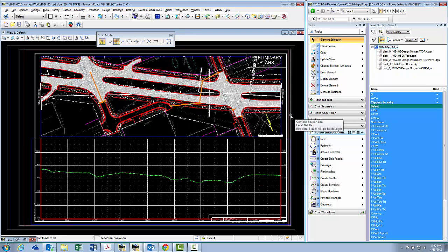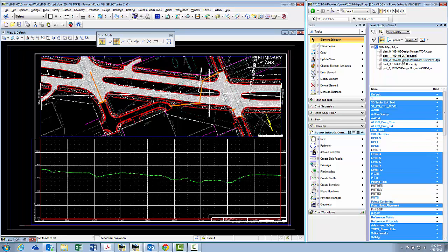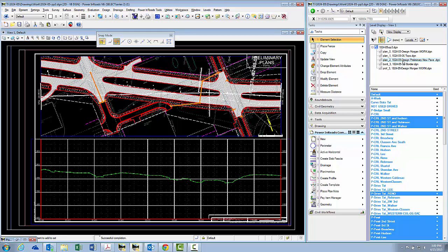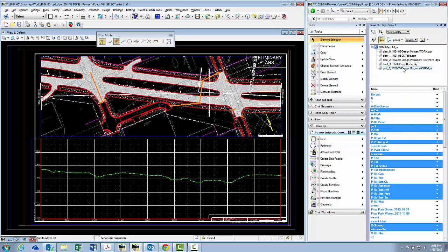So as you can see here on sheet 3, PNP Generator is only putting together your files for you so you don't have to do them by hand. So you can see that it referenced in the plan view my work file, the topo, and the design file exactly as I specified, and it referenced our PNP border with all of the levels off that I specified in the previous video. Also, it referenced in the profile the drawing that I placed my profile views in.